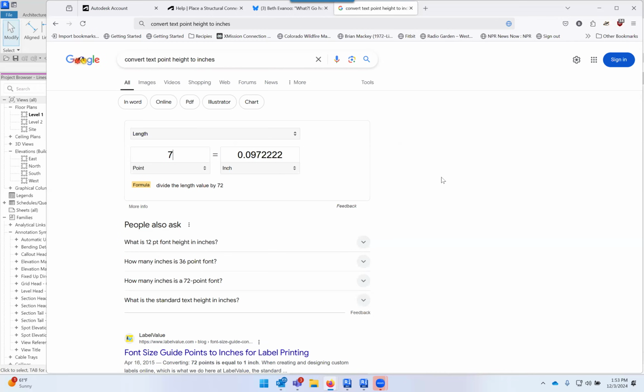And then as for column widths and column heights, mostly we're usually talking about the widths. With widths, they try to, again, interpret it the same way. So yes, I've had things where it looks formatted perfectly in Excel, you bring it into Revit, it's close, but it's not exactly the same. So that's all I got for you. And again, I used a couple different ones, but none of them I've found do it. And if you're using a lot of it, you just have to understand that you're going to get a weird, bizarre text style called import from Excel or PyRevit or whatever it is, and that's just what you're going to get.